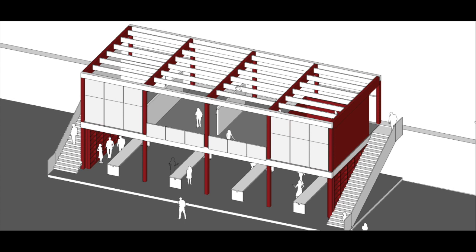Now, one thing to be concerned about is we don't see any bracing on the front side here. What we're counting on then, if we use the CLT, is that any load on this front face has to be transferred through and across both the floor and the roof in order to stabilize it. The roof right now doesn't have any lateral stability. So while this is a good option in terms of understanding the aesthetics, we know it's not quite done.